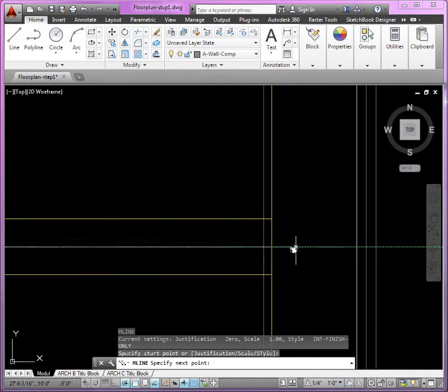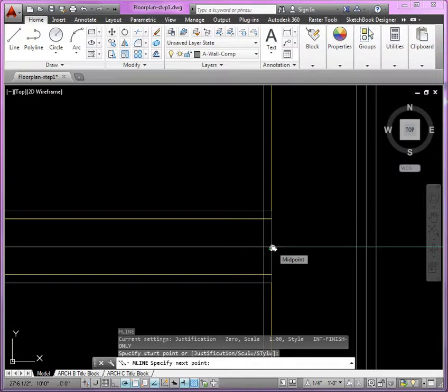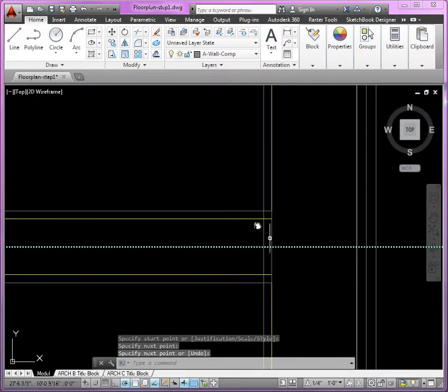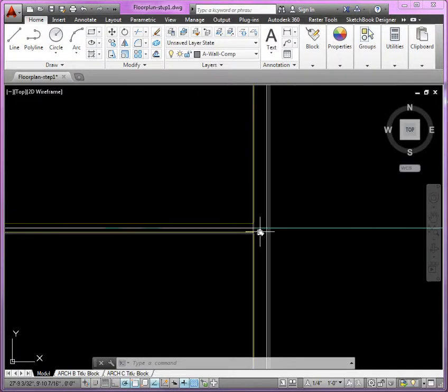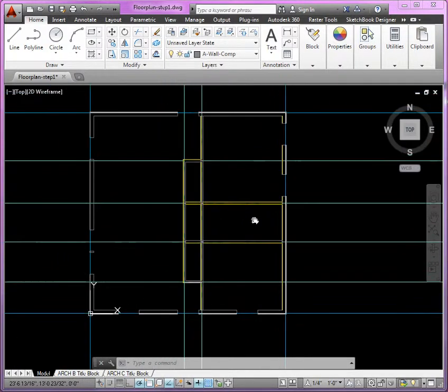Now, because I'm going to have to do this connection between the exterior finish and the interior finish, I keep it here because I want to show you sometimes also it may not recognize that it's an intersecting multi-line, and you might have to pull that line further into it or beyond it, again, to get the same results. So this brings to mind the question, well, do I need to be working with multi-lines? At any time, you can actually explode these lines. Just make sure all the line work is on the correct layer.